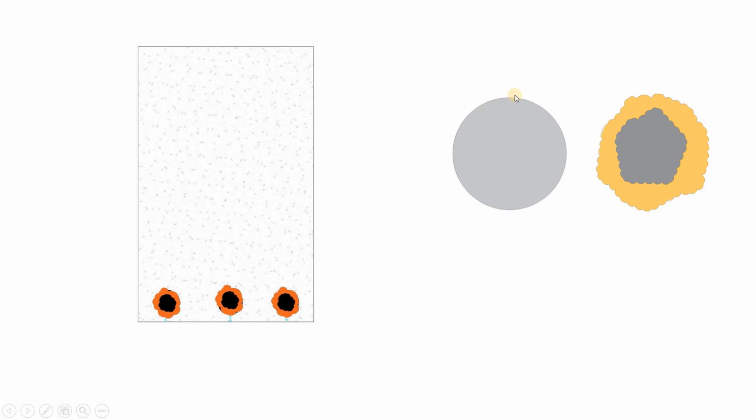By which the water percolates and this full-diameter circular reinforcement bar gets deteriorated and rusted, and as time goes on, this rust accumulates at the outer surface of the bar. So the core area only takes the load and the outer area doesn't take the load because it is rusted. By rusting, the round bar gets bulged, and the concrete portion near it gets much compressive force because this bar is bulging. So the concrete region surrounding this reinforcement bar gets additional stress due to the compressive force generated by this rusting.